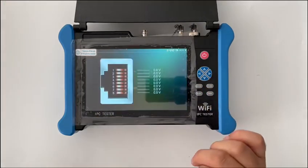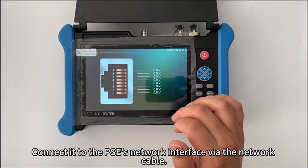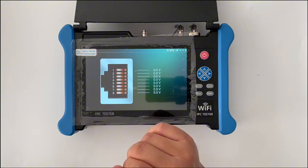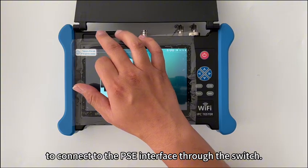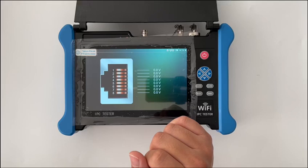PSE voltage test. This function is used to test the power supply voltage and power line sequence connected to the PSE's network interface via the network cable. Note: do not turn on the POE power of the instrument itself. This test requires connecting the first network cable to the PSE interface through the switch. The second one is connected to the LAN port of our device and connected to the camera. After connection, you can see the current PSE voltage test situation.